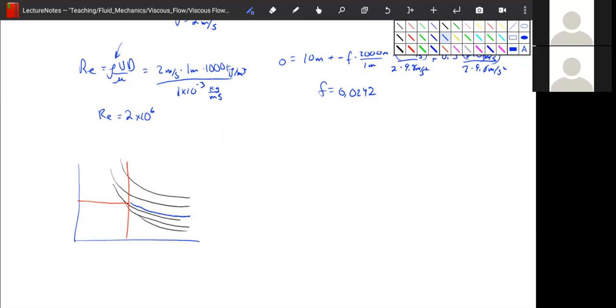If you have your implicit equation, it's no different than before. You just plug in the things you know and solve for your E over D. Same with the explicit equation. So go ahead, figure out one of the 3 ways, solve for E over D, try it maybe multiple ways, see what happens, and then hit play again. Okay, I'm assuming you did that. So E over D then, if you solve for it, ends up being equal to 0.002.